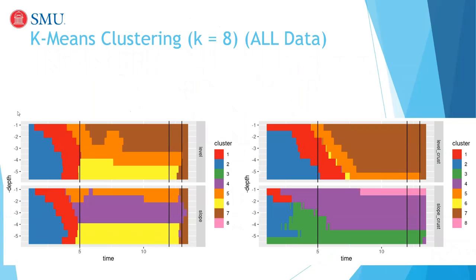So we took all the data, the ones from the level ground and sloping ground with no crust, and the data coming from the new simulations with crust, slope and level, combined everything and started clustering them to see how many distinctive features would appear. What we observed is that instead of the initial 7 that we had from the data science work, there was an additional zone, 8, this lighter magenta color, if you wish. And it's here, near the surface of the slope with a crust. This was another distinctive feature that was not observed in the level ground with or without crust, or the sloping ground without crust. This light magenta color only happened in the case of this impermeable layer.